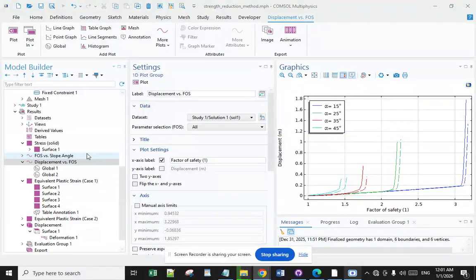The next concept is variant factors. Aerospace uses lower FOS where weight is critical, while pressure vessels and buildings use higher factors for more safety. Why is it used? The first reason is uncertainty. Material properties vary, loads are unpredictable, manufacturing isn't perfect.